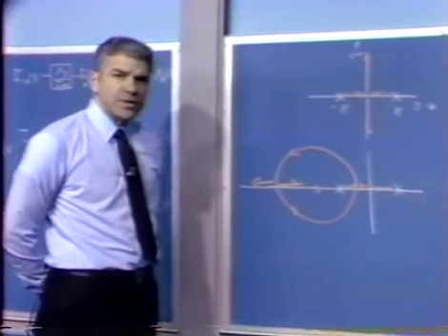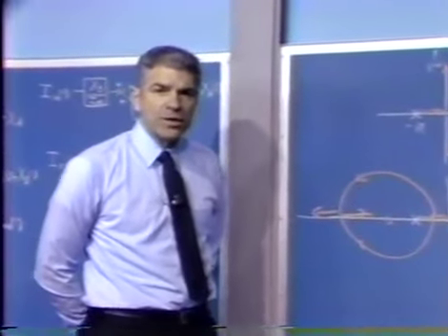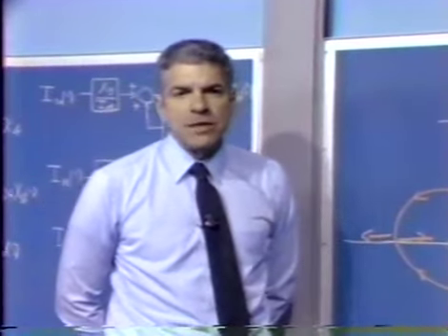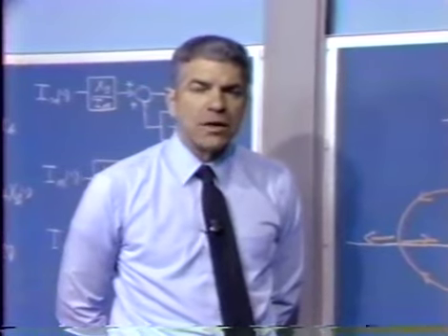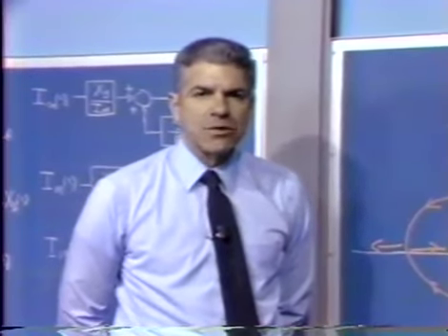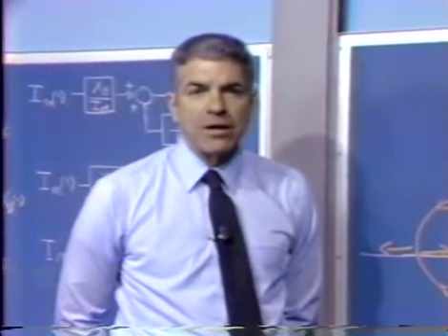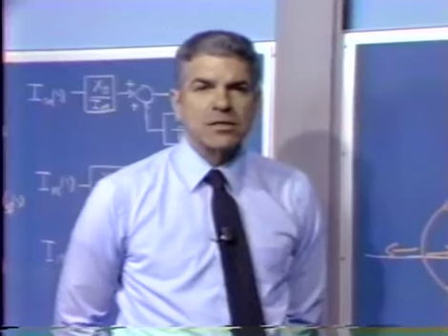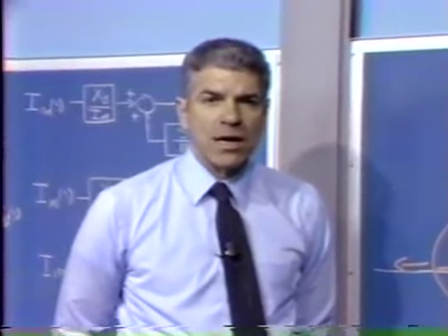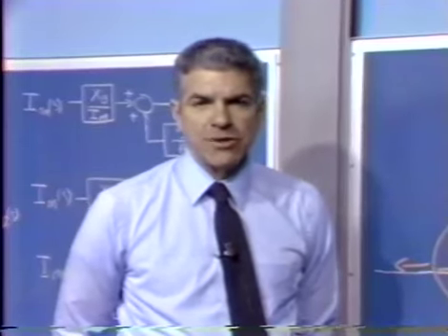The actual behavior of the system is a little bit more complex than this. There are additional poles beyond those associated with the dynamics of the ball magnet system. For example, the way that the position detection is done is using a photoresistor, and that's a device that depends on optical carrier generation. There's a time constant associated with that process, and so as the ball moves, the value of the photoresistor is not instantaneously proportional to ball position. There's a time constant associated with that, or at least to first order we can model it as a single time constant. There is incidentally also a nonlinearity associated with that relationship.